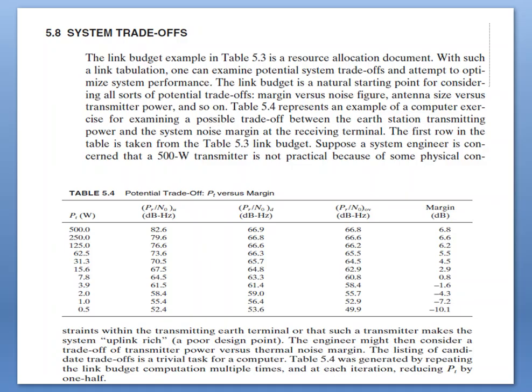Here the system is downlink limited, that is, the system is constrained primarily by its downlink parameters and hardly affected by the uplink parameters. In the bottom few rows tabulated below, we see that a 3 dB degradation to the uplink affects the overall SNR by almost 3 dB. Here the system is uplink limited, constrained primarily by the uplink parameters.